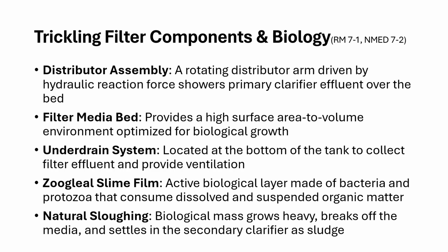So the rock that we use, or if we use any other filter media, it's not sand, it's rock that has a high surface area to allow the optimum amount of film with microbes to grow there relative to the volume. So we want to make sure we have enough surface area for this film to house those microbes and to have the wastewater trickle out over it so that those microbes are chomping away at the organic load.